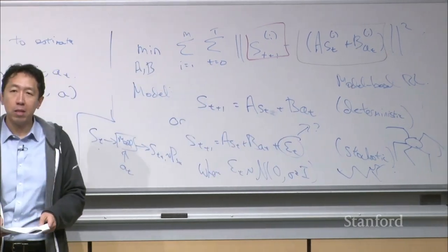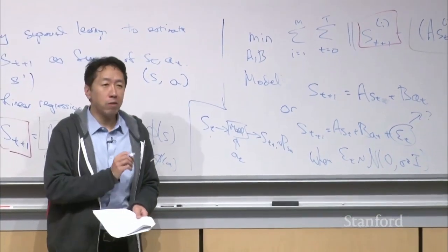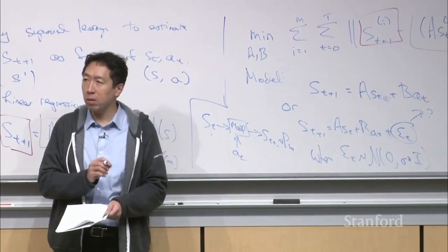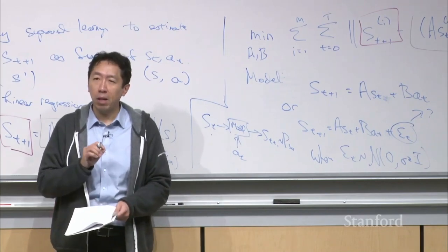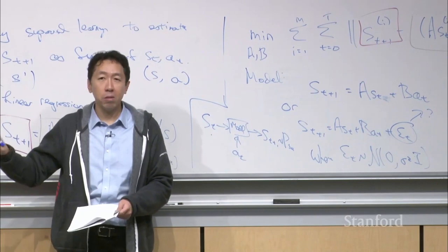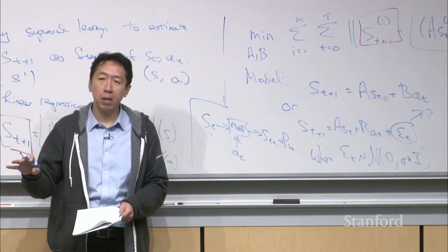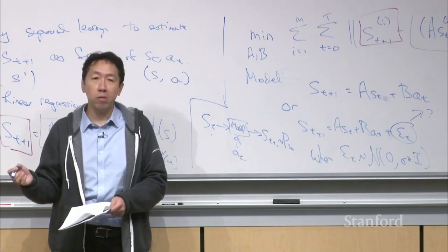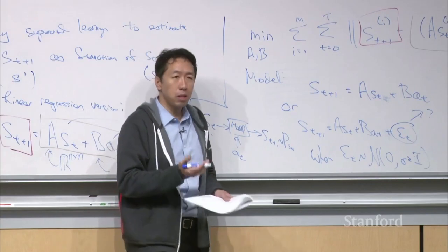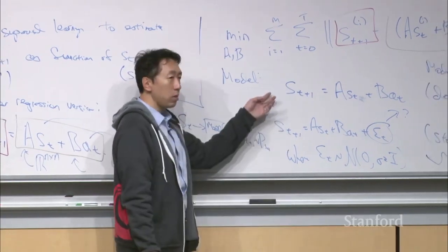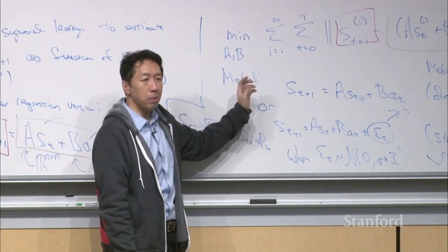But even though you can generate those types of videos in the deterministic simulator, if you use a deterministic model of a robot, and you ever actually try to build a physical robot, and you take that policy from your physics simulator to the real robot, the odds of it working on the real robot are quite low. Because your simulator is never 100% accurate, right? It's always just a little bit off.